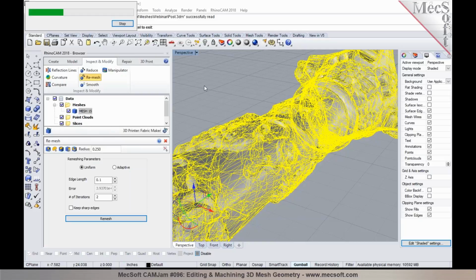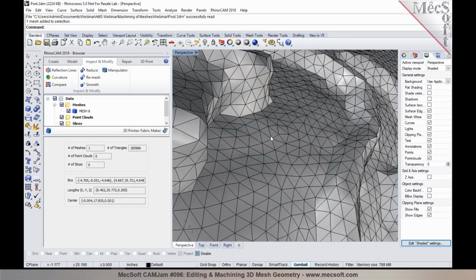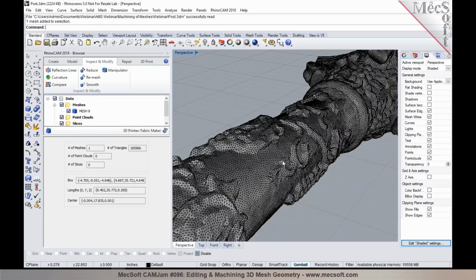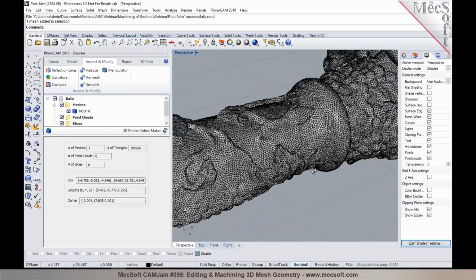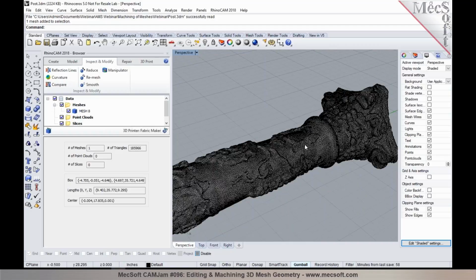You can see that it's processing the remeshing operation, and it probably takes anywhere from a few seconds to maybe a minute or so, depending on the complexity of the geometry. But you can see the speed at which it's being performed and the quality of the result that you're seeing here. It's much more uniform triangles that you generate on the mesh in here. You can also apply mesh smoothing and remeshing to specific target areas. If you wanted certain areas to be refined, you can apply those as we talked about in one of the earlier examples in here.